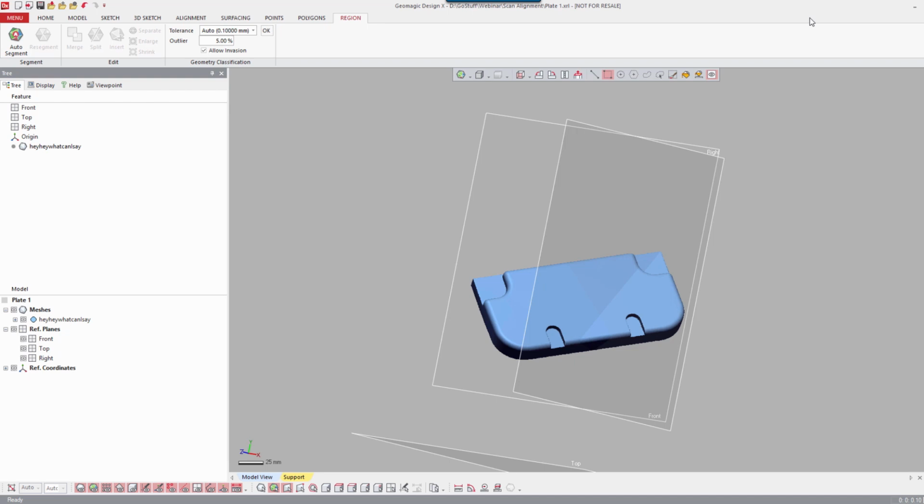You don't necessarily have to align your scan data, but frankly, it's a lot easier if you have planes that make sense, like the front, top and right, when you're doing your CAD modeling. You always concern yourself with the origin and make sure you've got a front view that makes sense. Same thing applies here. If you don't have a front plane, you can't orient yourself nearly as easily, or get started with sketching as well.